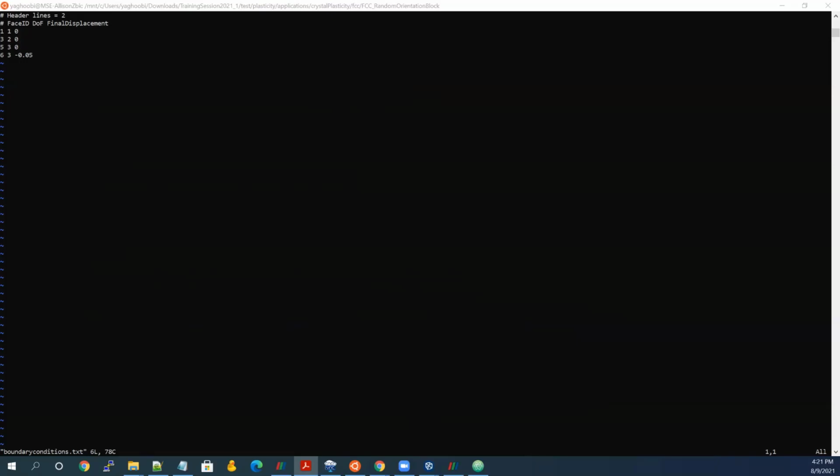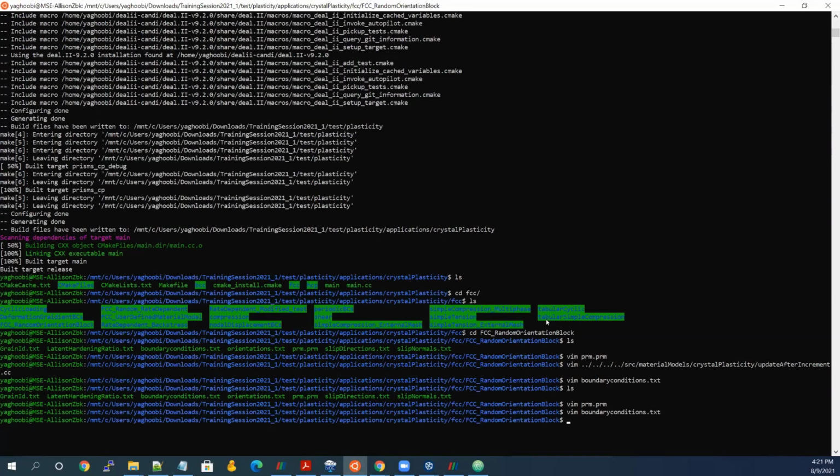The command you need to run this simulation now is mpirun -n. This is the command that we need to do: mpirun -n 6 main prm.